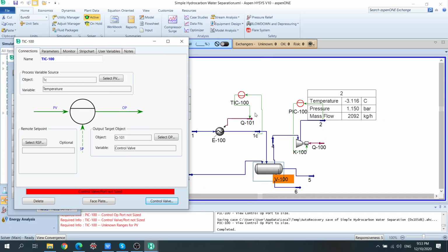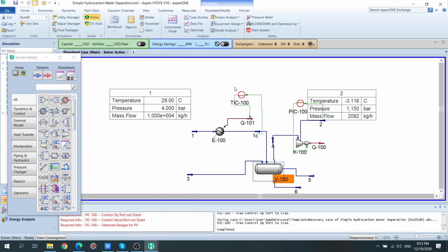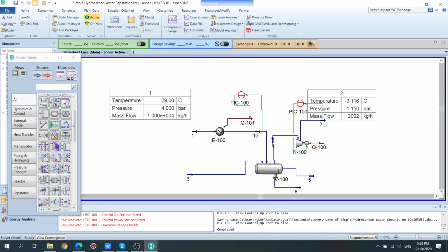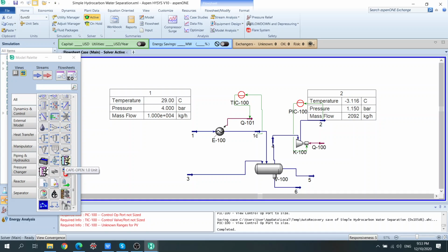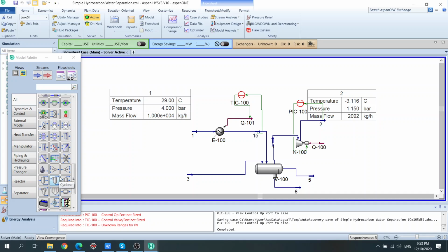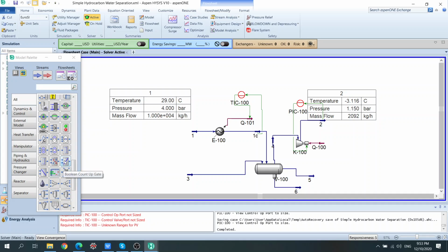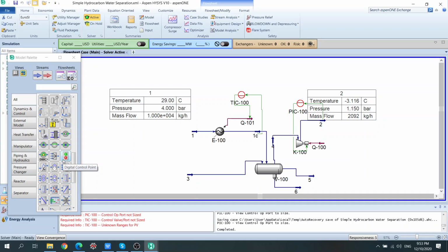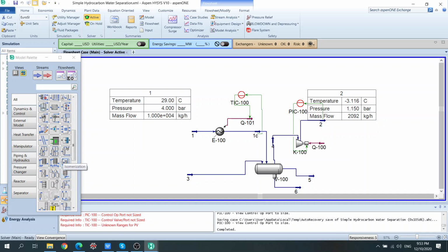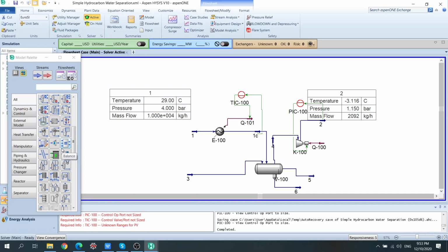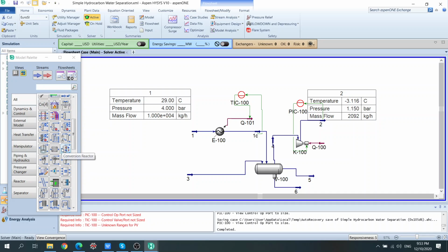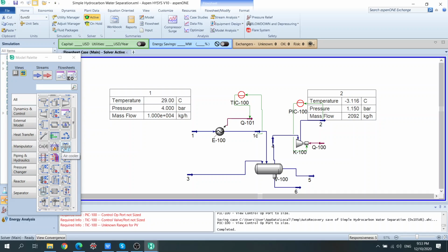In this case, we have to go back to thermodynamics. So okay, I will show you. I think we can see it here. One minute. What we need to do is find the correct operating conditions, pressure and temperature, in such a way that water condenses while the gas, these light hydrocarbons, is not condensed. That's the correct way to do it.